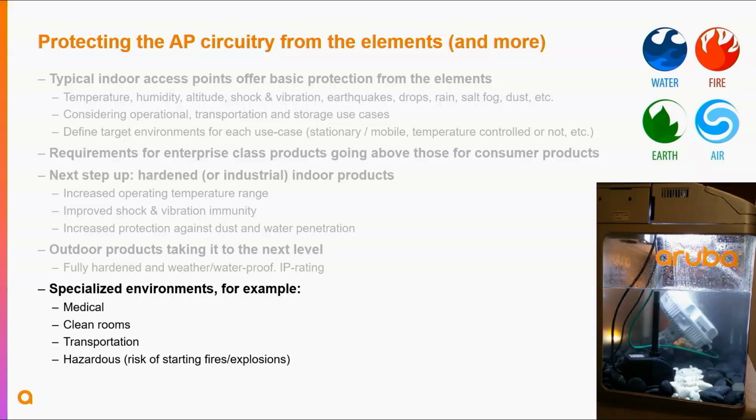Yeah, good point. So for these hazardous locations, there's actually a lot of requirements. There's things like impact tests that are done so that the AP doesn't break in case it gets hit by something, which I don't know why that's part of it, but that's part of it. The other thing is indeed, any interface needs to be secured, and there are very strict requirements. For example, all the Ethernet ports need to be attached to conduit. You cannot just put a cable and go with it. So we need to have an interface that supports conduit.